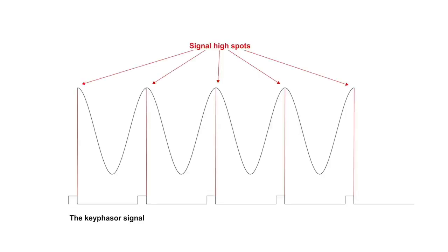What is the phase value? It is the angle delay of vibration high spot, means highest gap, after the key phasor position. Yes, I agree with you, such sentence is not understandable, but next pictures will explain it better. Here you can see the key phasor position is exactly the same as vibration high spot. The phase is 0 degrees.